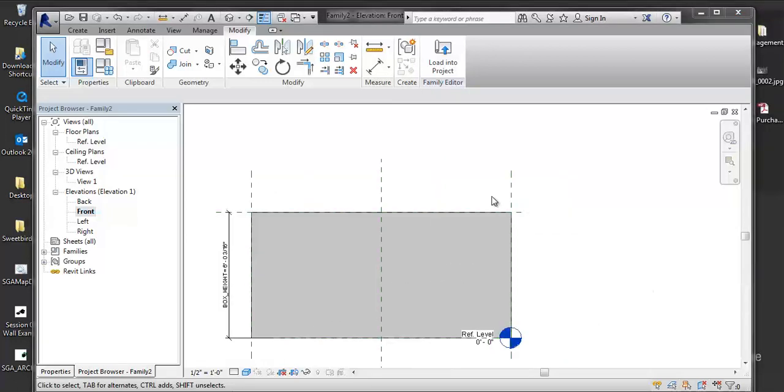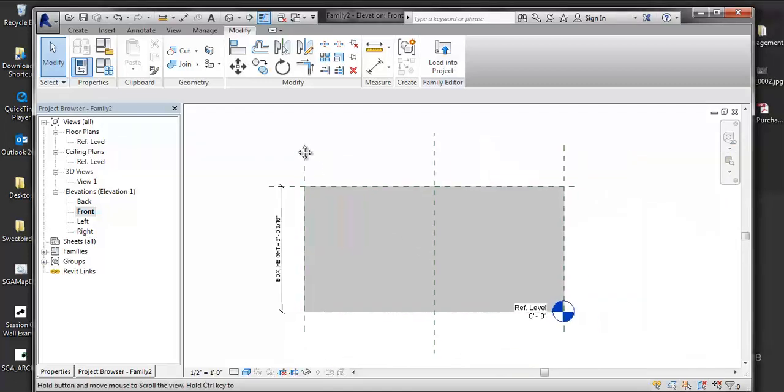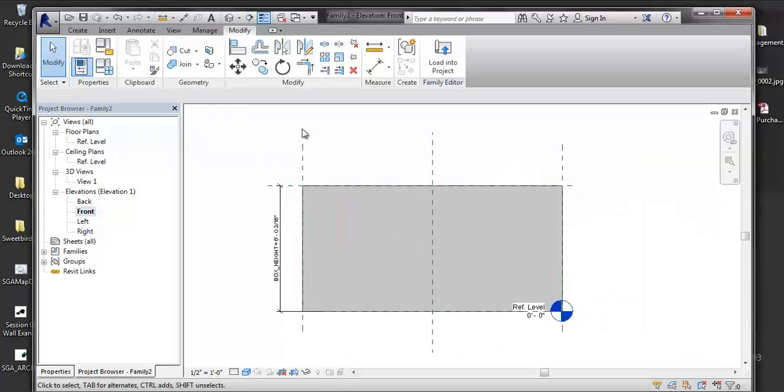We can get all that into this little box here, make a little Swiss box. Okay, so within here, I need to put a parameter called material, right? Material parameters and visibility parameters are not like the length and width. I can define them through the family types. However, I cannot do it associated with reference planes.